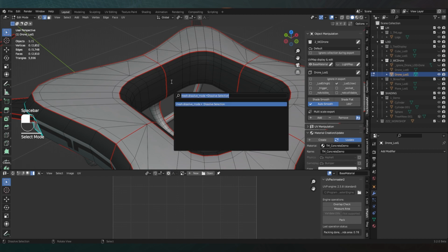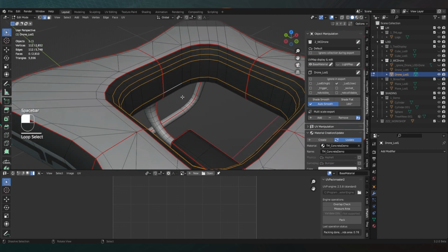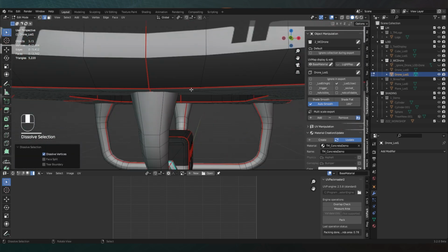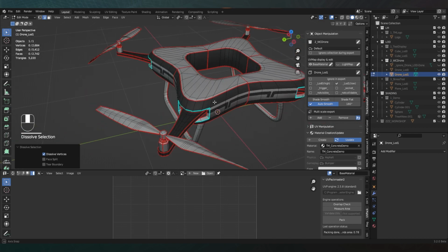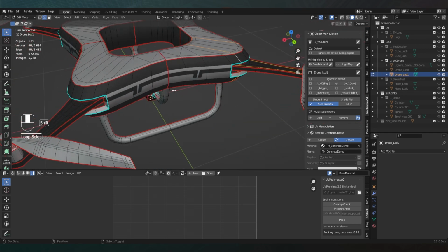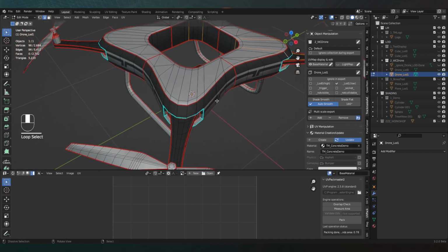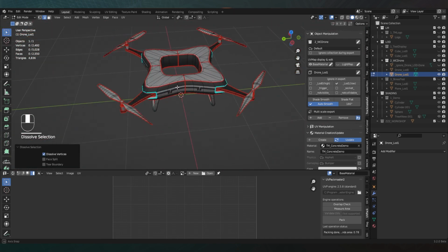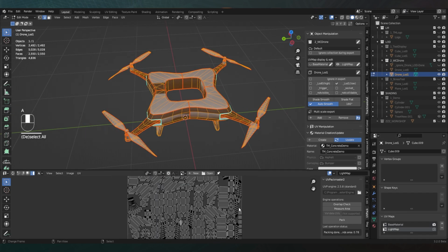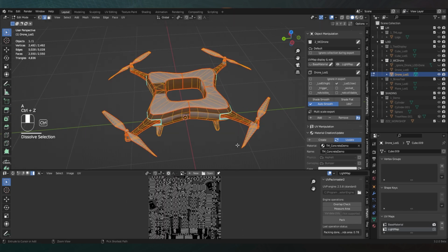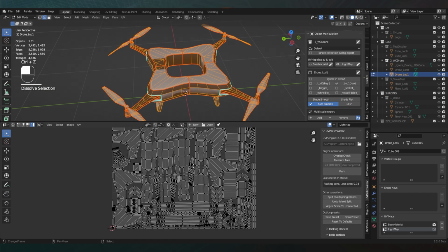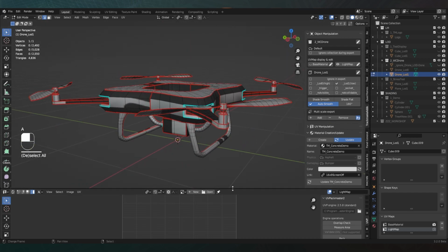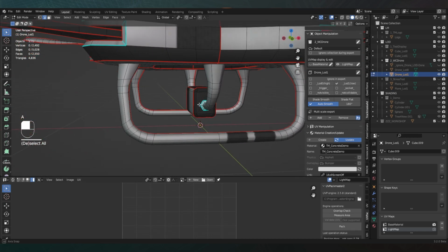So right here, we got a bunch of edge loops which make a smooth corner. It's not needed. You will not see that on different distance anyway. We can get rid of these outer loops as well. It shouldn't interfere with the light map. You can also just check if your light map is still okay. Oops. In my case, it looks still like the high poly one. So maybe check that sometimes in case you screwed something up.